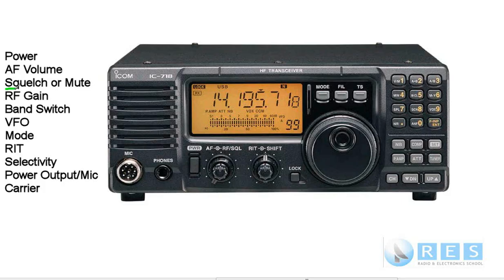The next one is the squelch or mute. It's called a squelch on AM and single sideband SSB, and on FM it's called a mute. The purpose of the mute is to remove any noise from the receiver when there's no signal being received. If you listen to a radio receiver and it's not receiving a signal, you'll just hear noise. So you can turn the squelch up to cut that noise off, and the receiver will be quiet until a